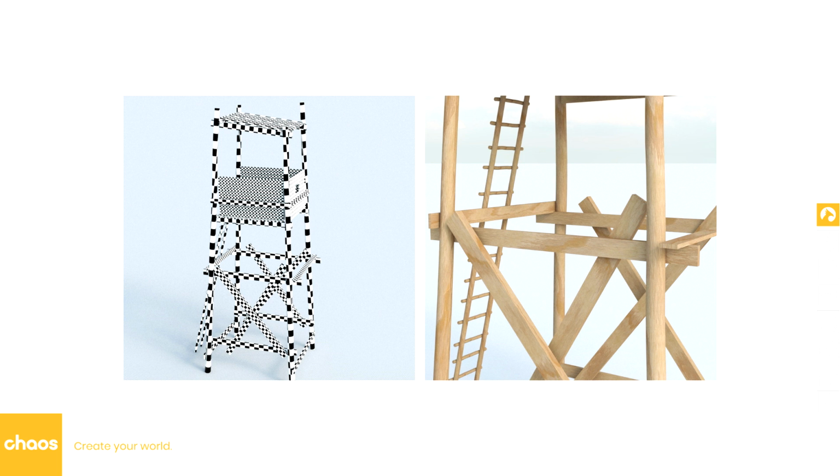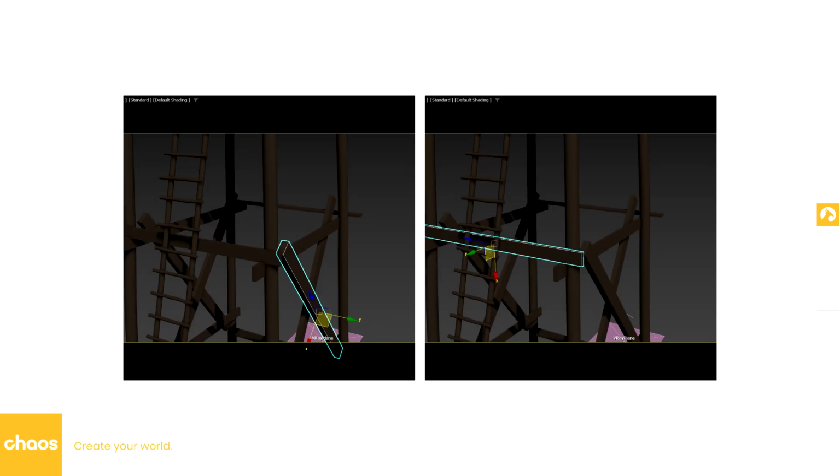As you can see, the wood planks are not overlapping, but positioned as if they were realistically nailed together. It's important to note that each component of the tower is a separate geometry. This allows for easy manipulation of its dynamics within the particle system. Furthermore, ensuring that the z-axis in local space aligns with the longest direction of each wood plank enabled me to utilize the volume break operator in thinkingParticles. This operator helped me fracture the planks into longer fragments, which we will discuss in more detail later on.